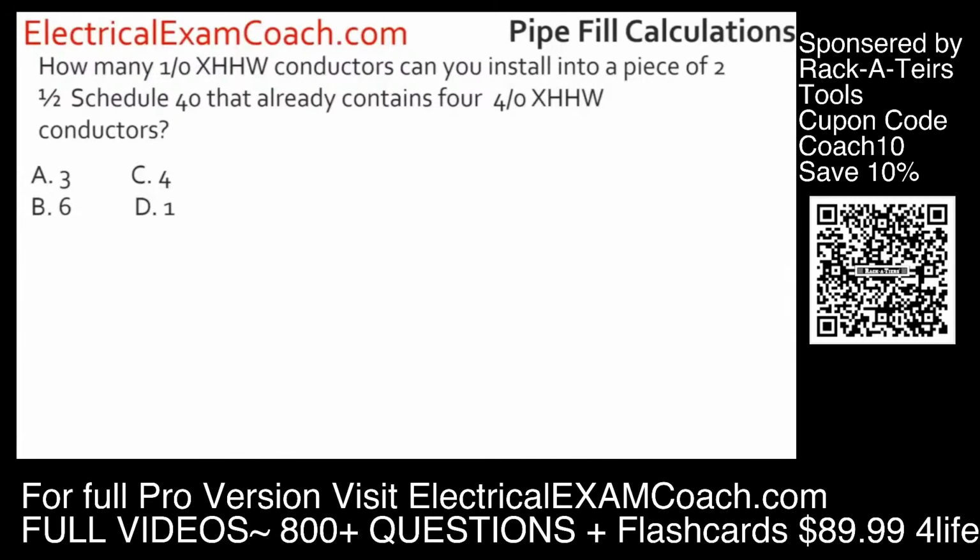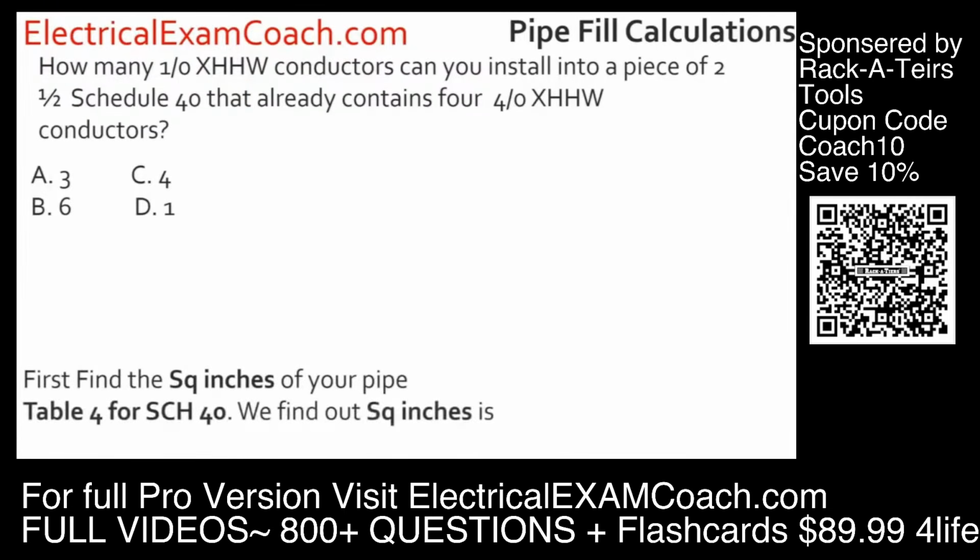How many 1/0 XHHW conductors can you install into a piece of 2.5 inch Schedule 40 that already contains 4 4/0 XHHW conductors? So the first thing we're going to find out is the square inches of our pipe. For that, we're going to head to Chapter 9, Table 4, for Schedule 40.